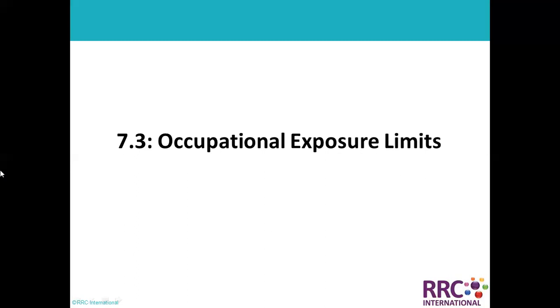I'm not trying to make this discussion more lengthy, otherwise I will start another technical debate. How will we ensure 0 ppm? How are we going to remove H2S from a confined space, or other toxic gases or fumes like carbon monoxide? How are we going to make sure even LEL is 0%? You are using LEL and UEL, lower explosive limit and upper explosive limit. And imagine, if you are doing hot work, what could be the LEL in a confined space?